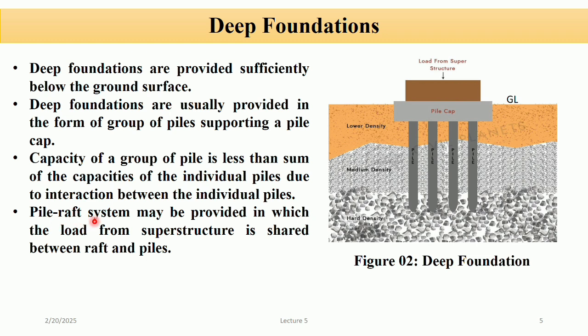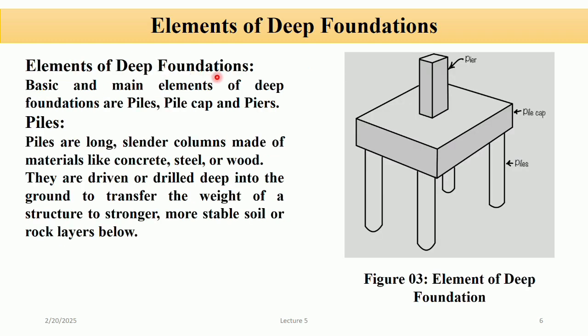A piled raft system is a hybrid foundation system that combines piles and raft foundation and soil interaction to optimize load transfer and settlement control. Elements of deep foundation. The basic and main elements of deep foundation are piles, pile cap, and piers. You can see in the figure that these are piles, this is the pile cap, and this is the pier. Now let's discuss these in detail.